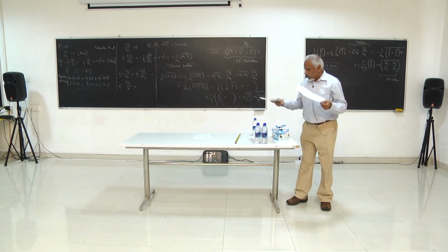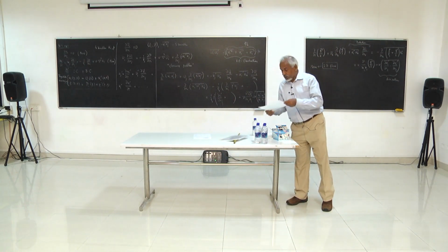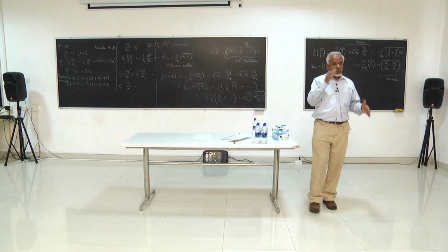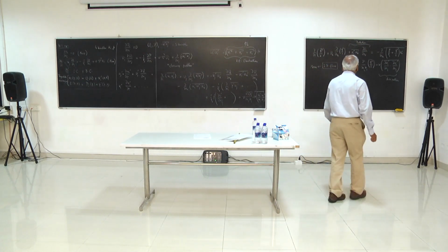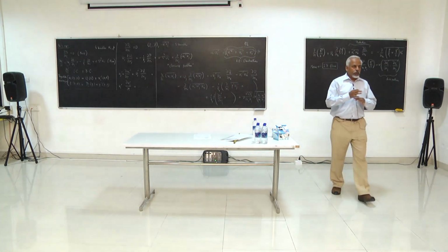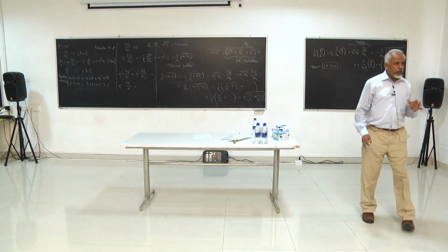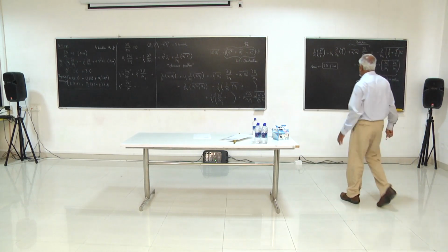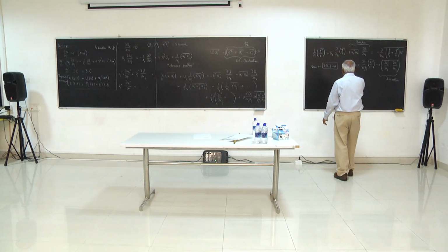But in the mean it is always the case. So mean velocity is two-dimensional. But the fluctuations could be and would be, in fact, in all three directions and roughly equally. And I will want to tell you why it is so in a bit.